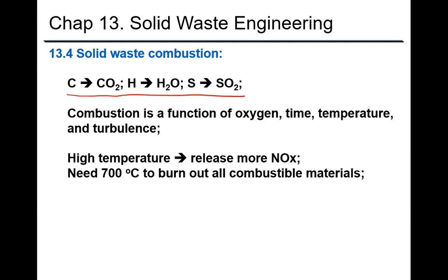So combustion is a complex function of oxygen, time, and temperature. As we introduced earlier in the NOx control, we don't want to use a very high temperature because the higher the temperature, the higher the NOx, right? But for the combustion of waste, we cannot really burn it at low temperature because then we cannot use all of the combustible materials.